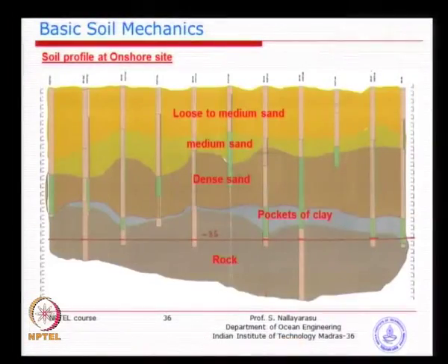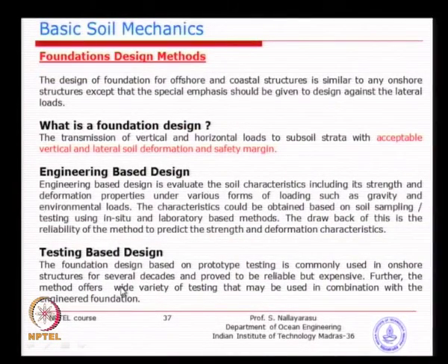So, you will go back and change the parameters of the strength of the soil iteratively, because you do not know which layer has contributed higher or lower, unless you have the layer wise result, which is very hard to get, because the pile load test will not reveal such information. You have constructed the pile to the total depth and then you have done the testing. It is not like every time you drive a little bit you do the testing, which is also not feasible. So, that is why the testing based method is very helpful, because you collect information from prototype testing, use that to correct your design parameters and calculations backwards, again come back and find out what is the penetration required.